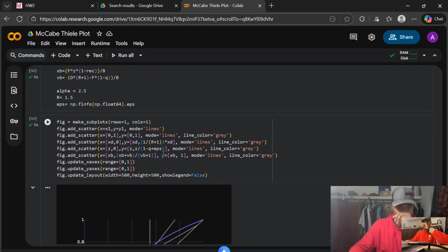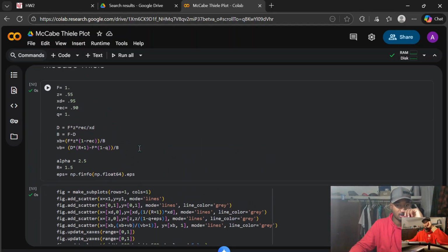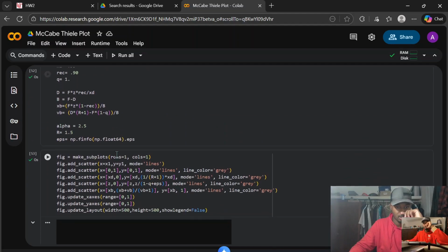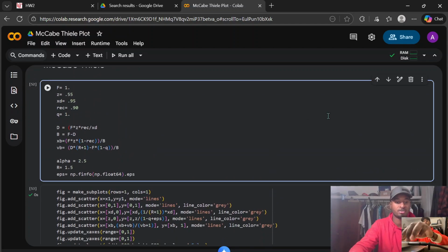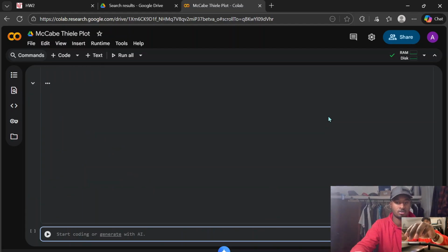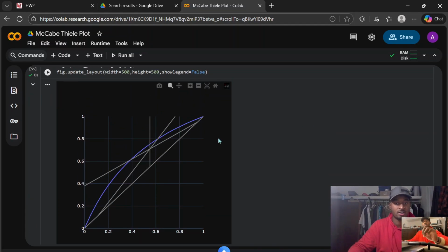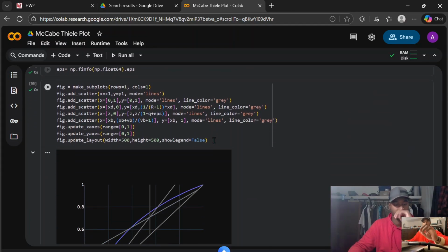Also I used the wrong equation for the rectifying section. I mistakenly put R here, so that wasn't correct. I need to look at the second part of the equation, which is 1 over R plus 1 times XD. And then another thing that I messed up on. Oh, where's that? Yeah, for calculating the distillate flow, for some reason Python did not like that I used parentheses here. Or I guess it doesn't matter. Never mind. So those are the errors that I found in those calculations.